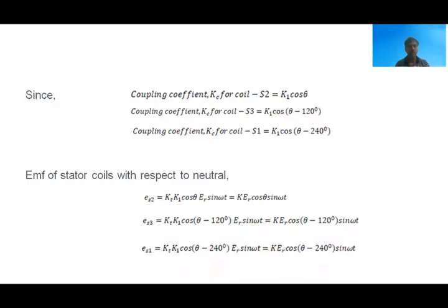Therefore, for the EMF of the stator coils with respect to the neutral terminal, since all the stator windings are connected in star connection, the EMF induced in the stator winding S2 is equal to Kt K1 cos theta, where K1 cos theta is the coupling coefficient, into ER sin omega t, that is equal to K ER cos theta sin omega t, where K is the constant which is equal to Kt into K1.